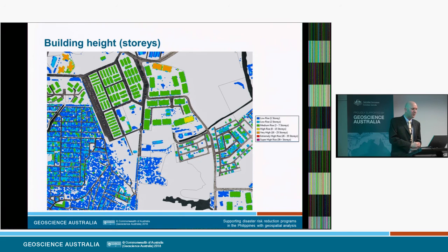And so the result of that for each grid cell is the height at that part of the building expressed as a number of stories. And because each of those cells are 1 square metre, we then actually have the floor area at each of those cells. So that's great.